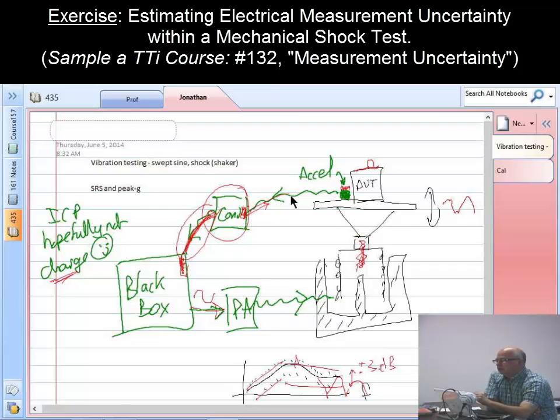This cable here, though, now is carrying a charge. We're trying to sense the charge generated off the transducer going into the conditioner. And so calibration will change with length, as opposed to the ICPs when it's a voltage current. I've had a 2-foot cable and gone out to, I forget, 200 or 400 feet, and I could see no discernible change in calibration, whereas with a charge cable, length does make a slight issue. Also, it's very, very susceptible to pickup of electronic noise and that triboelectric effect.